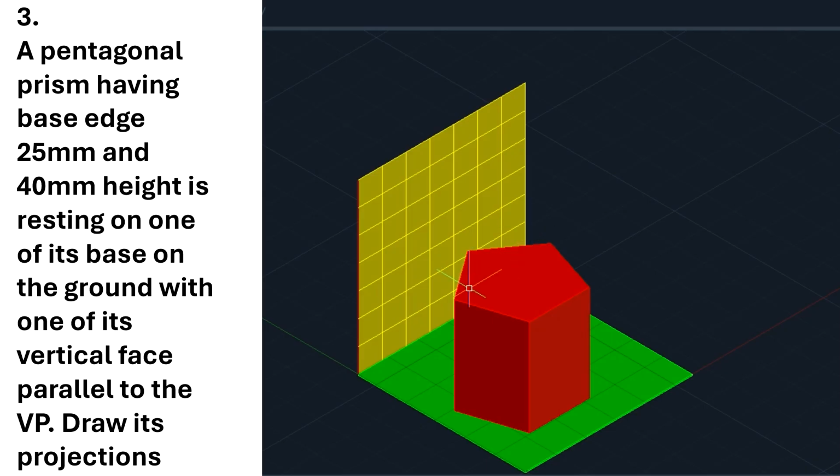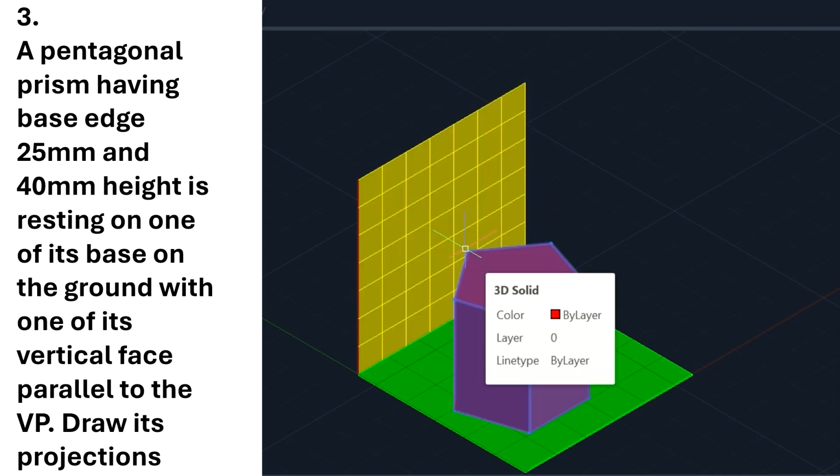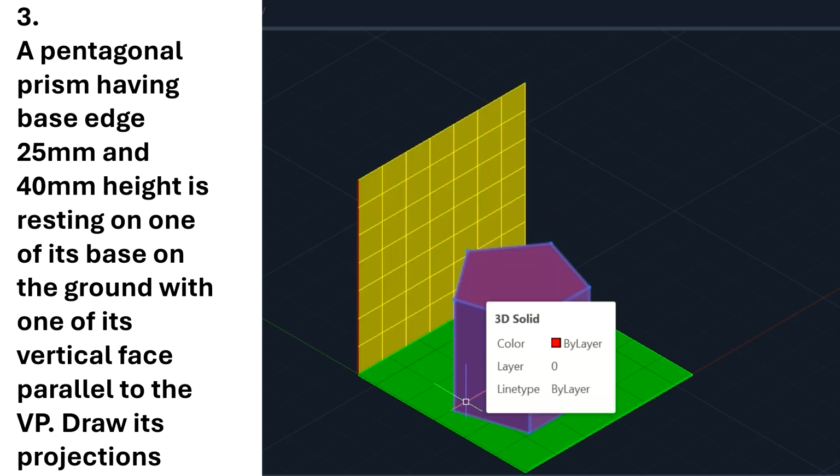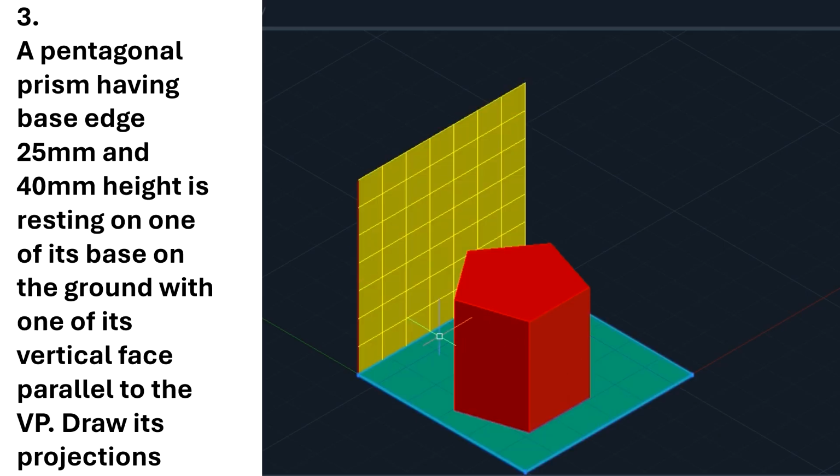As I already told you, if you take the leftmost corner and rightmost corner points and draw a line, whatever portion is on this side will be visible, and the other side of the solid will not be visible. So this edge, 5E, will not be visible in the front view. So we will mark that edge as a hidden line.